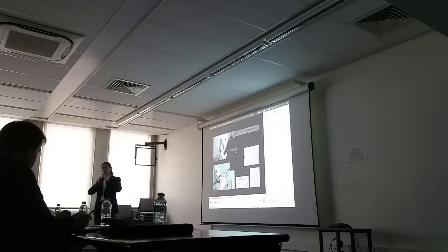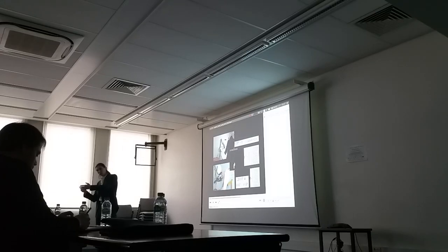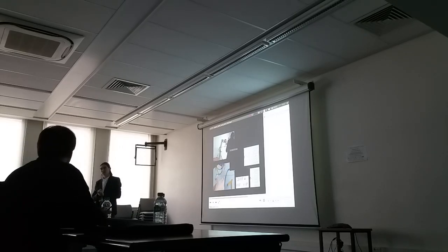And due to these changes, the end effector pose itself does not change. So the stiffness parameters of the end effector were chosen to be high enough in order to not take into account the compliance of the sensing surface of the sensor. Okay, very good. Will it be a problem with the Shadow Hand?